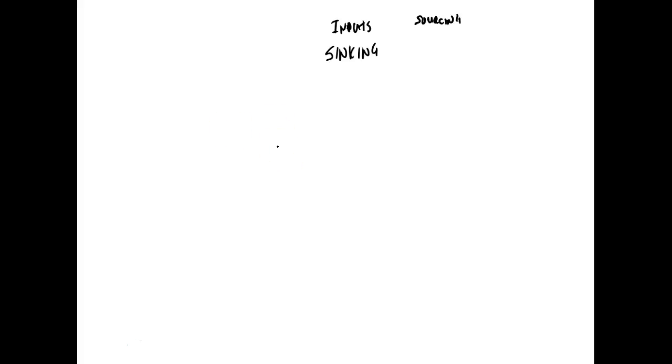On the MicroLogix PLCs, you don't have the ability to hook up all your inputs as sinking or sourcing. They divide them into groups.